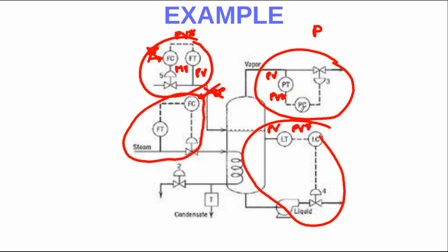Here we have the PC, which is the controller. Again, the set point is internal, and this is applied into a valve. As you can see here, again, the diagram is also simplified because here an I to P block is missing. The name of this block would be PY according to the norm.